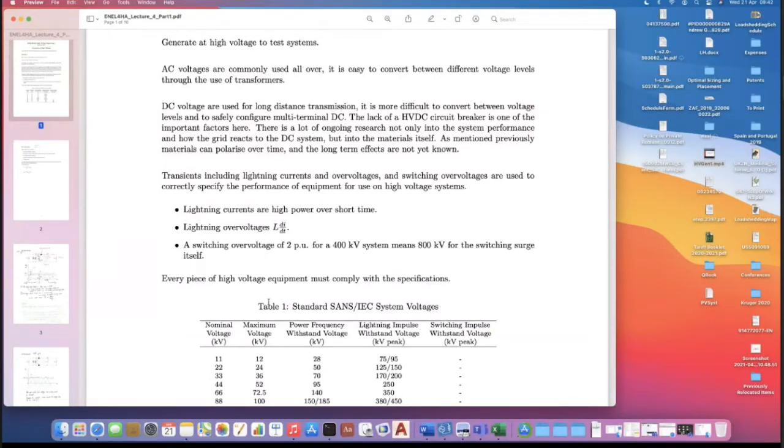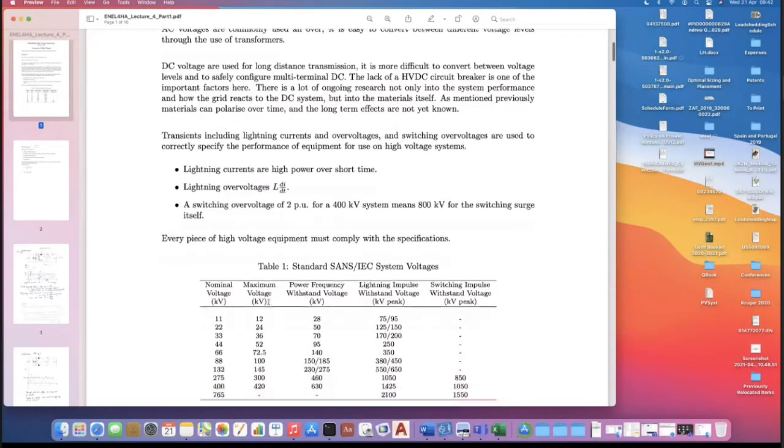And that's fine for low voltages because normally it's not high enough to cause problems. But when you start looking at high voltage systems and you close a circuit breaker onto a big transmission line, these switching over voltages move up and down the line. You've tackled traveling waves elsewhere, and that causes additional issues. And we need to account for that.